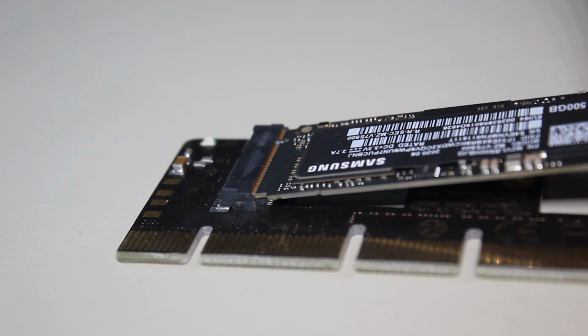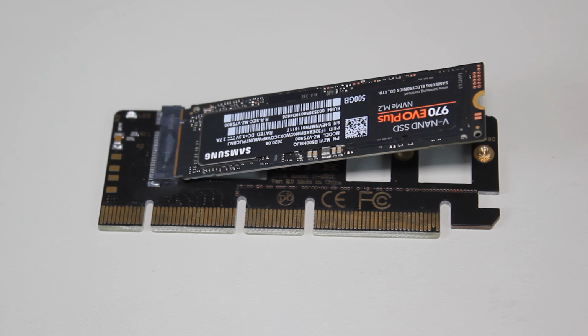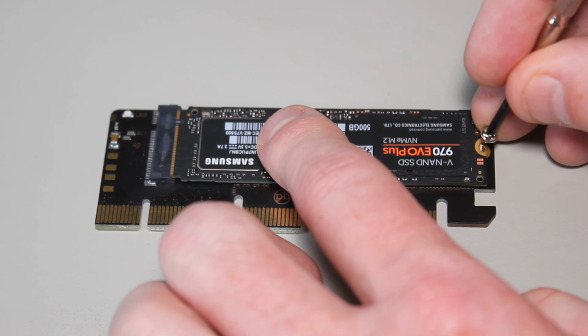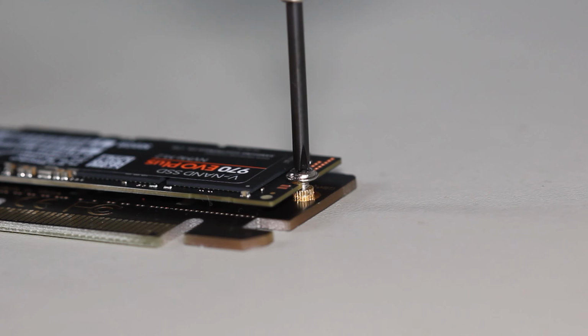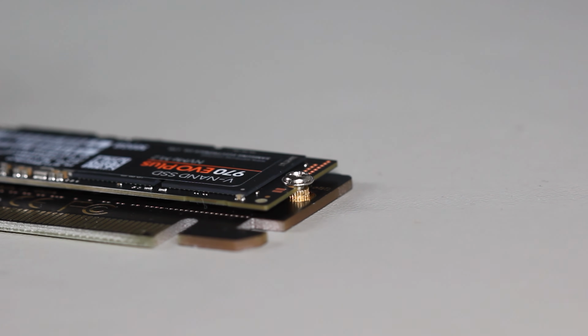To install, insert the M.2 SSD in the connector at about a 30-degree angle. You will need to wiggle or push the board a little to get it into the controller. You should not have to apply too much force. There is one screw that holds the board in place. In order to put the screw in place, push the board down so it is flat, and then screw the screw into place. If everything went correctly, the board will be flat. Later in the video, I will look at one of the cases where this may not occur.